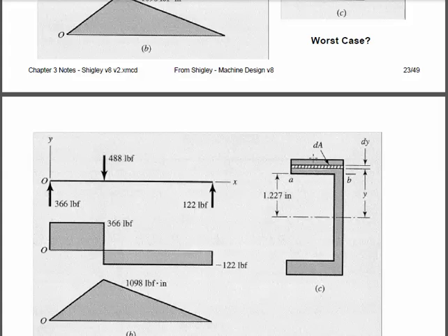And the integral, or the Q value, is the area above this cut line multiplied by the location of the centroid of that area above the cut line. So it is an A times the centroid location. And so what makes the shear stress interesting here is we've still got lots of area, and that y bar quantity is large, because the centroid would be right about where that dashed line is. Why would we have very little shear stress, or very little Q, at the top? Because although the y bar piece is quite large, the area piece is small.